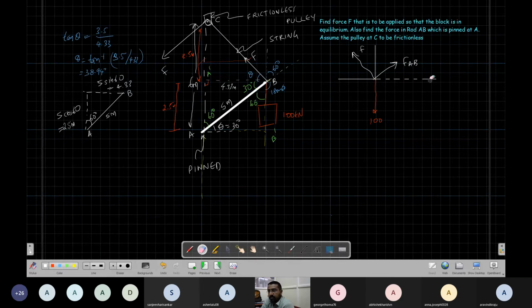This is my axis. Okay. So then what I will do, I will find these angles. This angle I already know it's theta. We already found theta. And this angle, I don't know what it is. This angle is about 30 degrees. This is the 90 degree angle. This is 30 degrees. Okay. Now if I do this, this could be a slightly simpler formula. This also is okay, unless Lami's theorem, you can do any method.